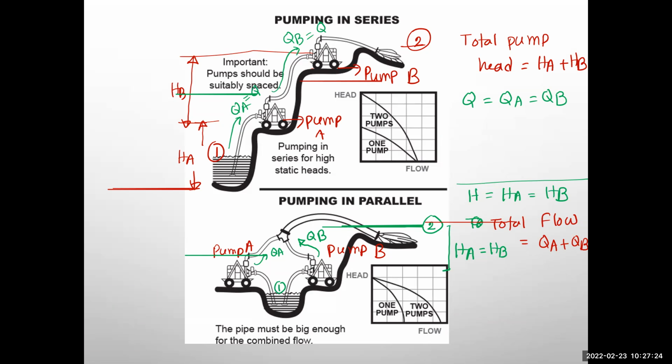Now my question to you: if I need more head or more height in the system, should I add the pumps in series or parallel? In series, because I'm getting more head.